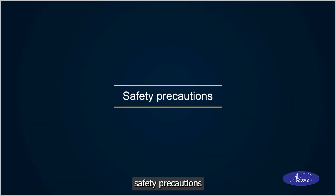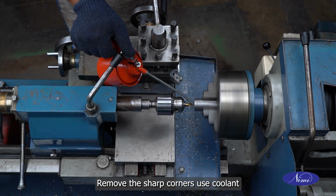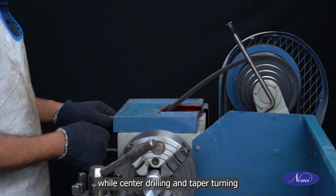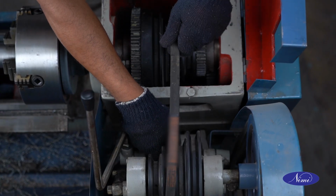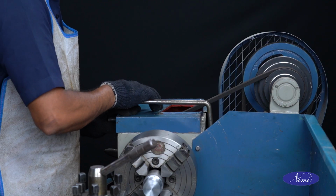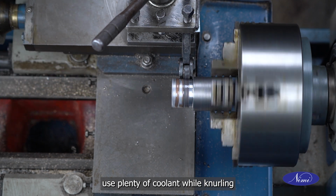Safety precautions. Remove the sharp corners. Use coolant while center drilling and taper turning. Use slow speed while knurling. Use plenty of coolant while knurling.